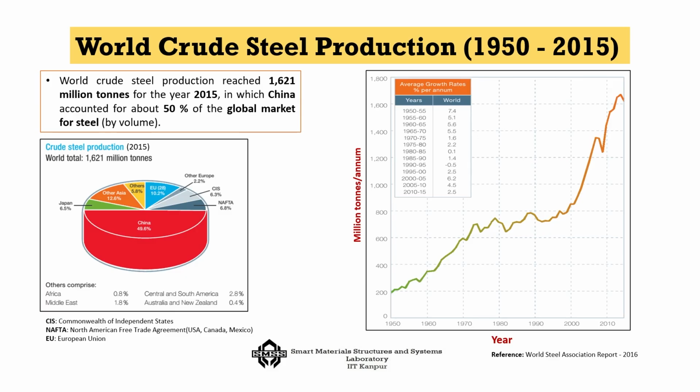If we keep that point in our mind, then what we can do is heat up iron, take it to a particular crystal structure and then quickly quench it to retain that structure. So, the benefits of that crystal structure we can extract. So, that is why these phases are important for us. Now, today what is the scenario?